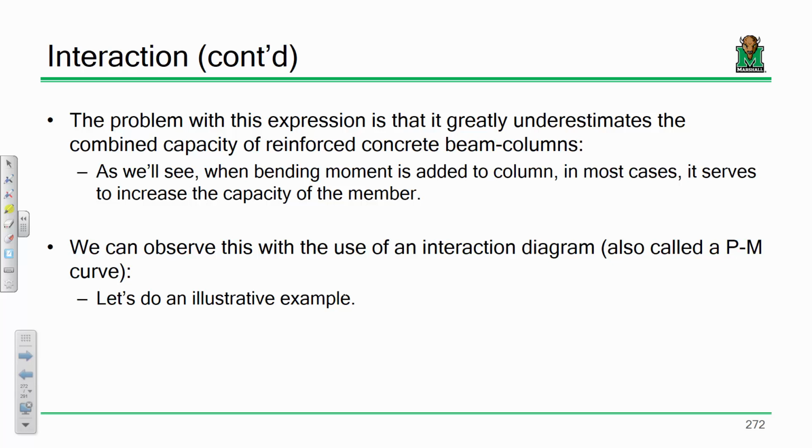Okay, so imagine if I took that beam and I applied some compressive force to it. Do you think its bending capacity would go up or go down? It'd go up, right? That's the main fundamental principle of pre-stressed concrete: concrete does not like tension, so we'll just apply extra compression to it. And you can actually get additional capacity out of a reinforced concrete element if you apply additional compression, okay?